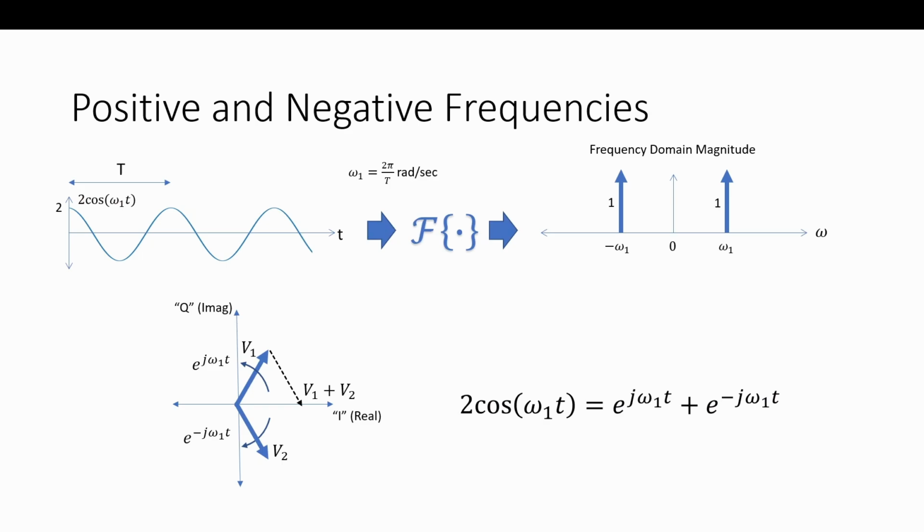So this one that's negative frequency, e to the minus j omega 1 t, right here is rotating. It's the phasor rotating clockwise, and that's in the time domain. The Fourier transform of that alone is a single impulse in frequency. So you rotate in one domain, it shifts you in the other domain. So that works in both directions. That's how you work with phase. So we have two of them. Then we have one that's rotating counterclockwise. That's the positive frequency. So think of frequency as bicycle wheels, and now we can tap direction. Now we can tap positive, negative.